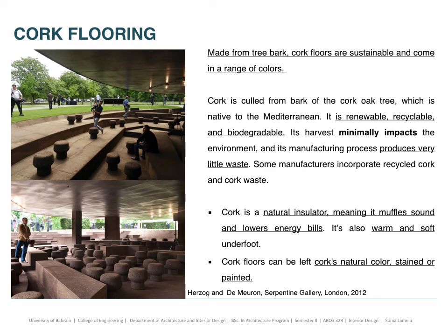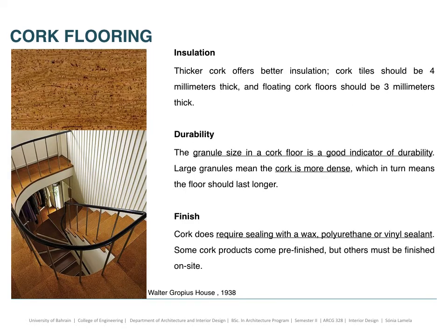The cork flooring is good for insulation. It's also very good for durability. Of course, larger granules mean that the cork is more dense than the smaller granules. For the finishing, cork does require sealing with wax, polyurethane, or vinyl sealant.